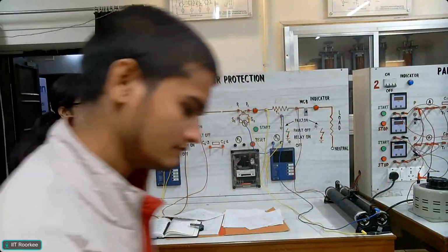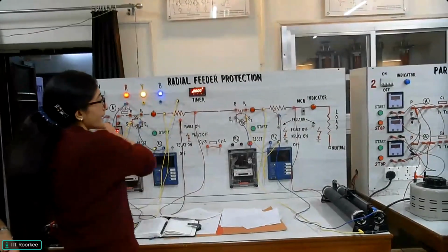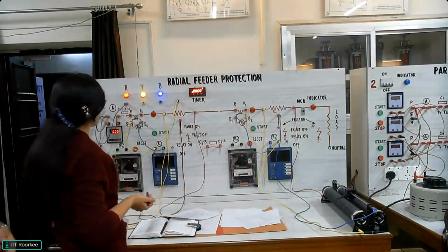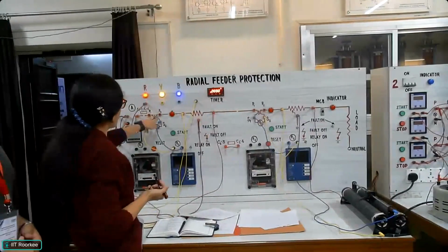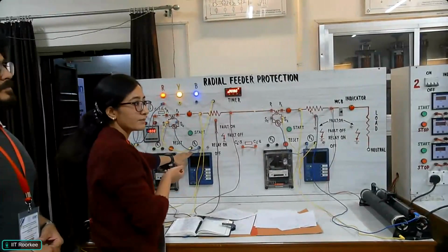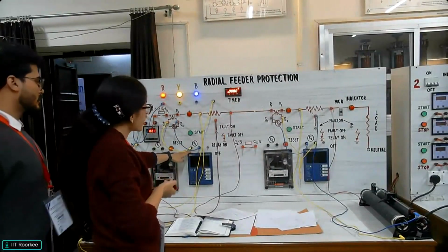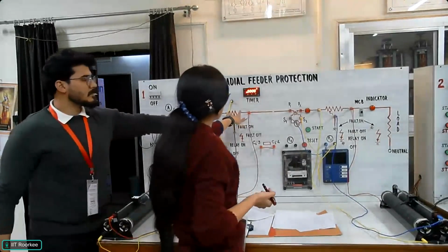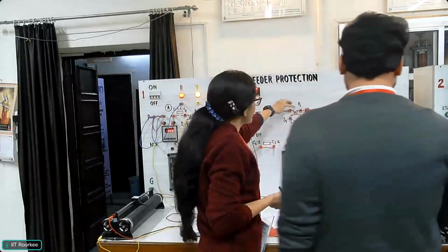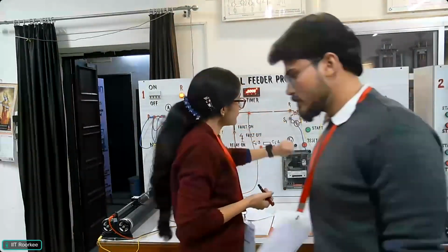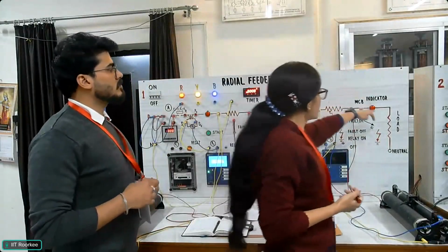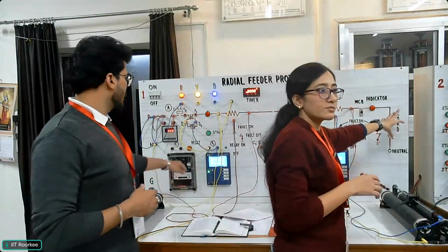Okay, so here consider a supply source to a load. The load is like a consumer. So this is our 230-volt supply. Then the CT is connected here, primary, and with the CT secondary, our measurement or sensing devices are connected. So this is our relay. Then this is one feeder of 6.5 ohm. Then another feeder, same configuration, CT, and from the CT secondary it is connected to the relay. Then we have designed a load side, maybe the consumer side.